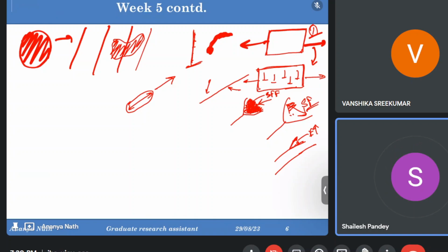Okay, ma'am. So this was the concept of cross slip and climbing. Climbing is used for edge, and cross slip is used for the screw dislocation. Also, the dislocations need to have a common slip direction to move.